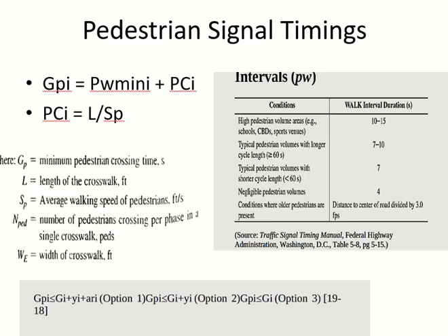For this guy, you don't have any factor of safety. Right? Okay, but if I made the green of the pedestrian equal to green plus yellow of the cars, now this slow pedestrian has 2 extra seconds of factor of safety. Even if he is late by 2 seconds, he is still safe.